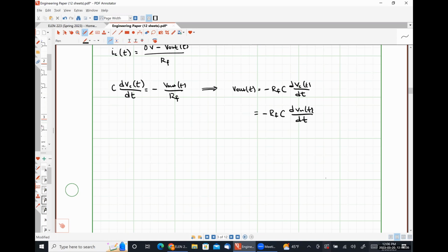So instead, and we don't really do this in the time domain, in the frequency domain, we would relate these two quantities, the input voltage to the output voltage, by what's called the transfer function of the system, where the transfer function is literally the ratio of the output voltage to the input voltage. And it will depend on frequency, which would be true for these if we weren't looking at them as a function of time. So short answer is, yeah, the gain doesn't matter, so don't worry about it.